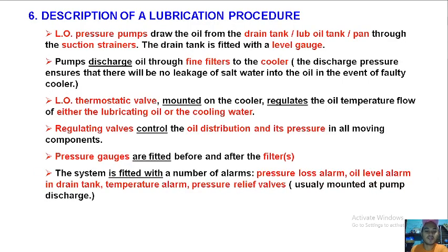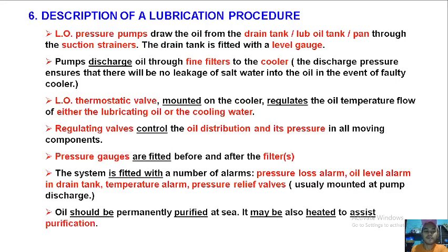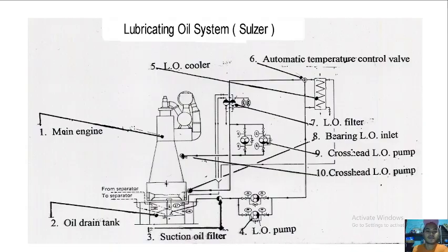And then the system is fitted with a number of alarms: pressure loss alarm, oil level alarm in the drain tank, temperature alarm, and pressure relief valves, usually mounted at the pump discharge. These are protections for the system. Then the oil should be permanently purified at sea. It may also be heated to assist purification. Even at port, the purifier is still running.